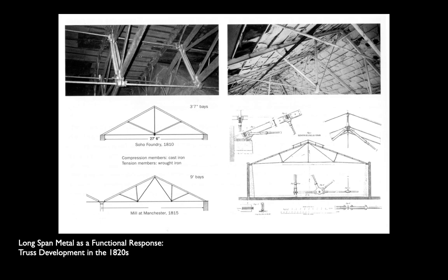We've seen that Palladio, in his bridges, understood the basic principle of triangulation, but here we have a material in wrought iron that's really, really good in tension, can take much more loads with much, much smaller or thinner elements. And the drive to kind of make those as small as you can, to use as little material as you can. This is a great case of optimization. The theory of truss design develops when we get a material like wrought iron that can take tensile loads in enough quantities that it's kind of worth calculating, right? Seeing how much they can actually take.